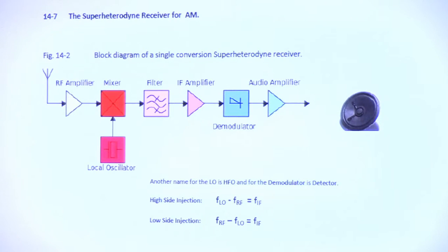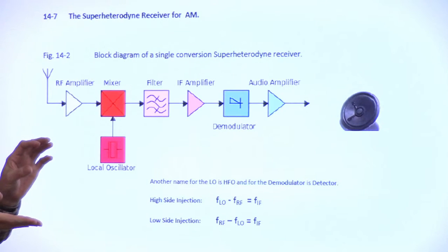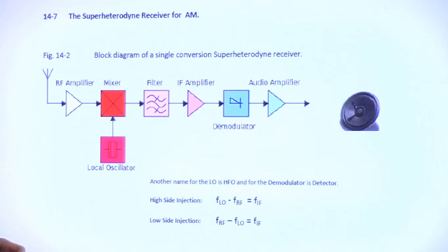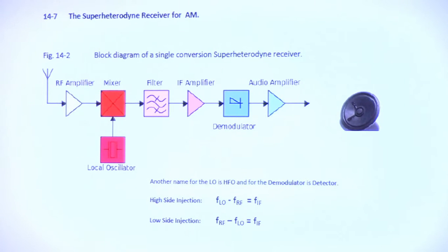So what we can do in a radio is build a section called the intermediate frequency section. It's always going to be the exact same frequency. Typically the one you'll see most common back in AM radios, still used to be 455 kilohertz. So if we can convert any signal we want to receive down to that one band, we can put some really, really good filters in that one section, because all we have to do is build filters for that one frequency band, one bandwidth, in our case, say 455 kilohertz. So we can use what they call crystal filters, mechanical filters, very sharp, very good filters, because all we ever have to do is filter at that one frequency.